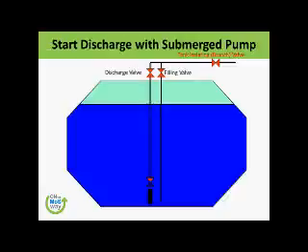Okay, we have got another method of doing this thing: whenever we start this pump, we start discharge and we throw it back into the tank. We recirculate for a while till our pump is settled down, the temperatures of the pumps are settled. Because whenever we give a starting current or a starting torque to a pump, the pumps get very hot. And of course, it needs to come back to its cryogenic level, which is minus 161 or 162 degrees temperature.